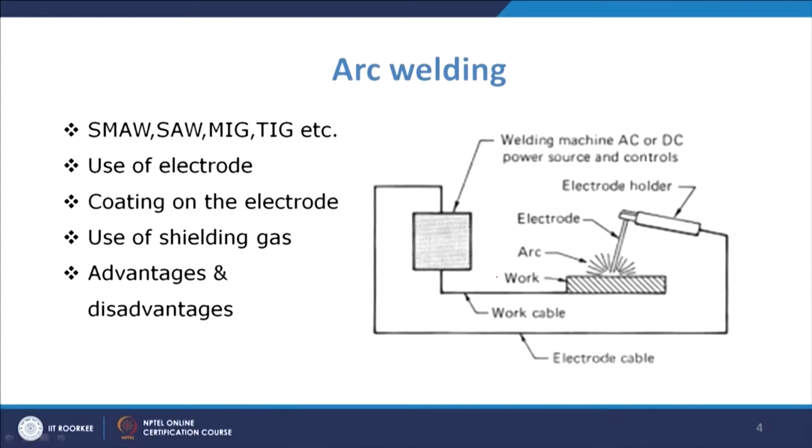So, another method, which is the most popular method, is the production of an arc using electrical energy. In that case, the arc is created, that is nothing but an ionized plasma, between the electrode and the workpiece. This arc has a sufficiently high temperature close to about 6000 degrees centigrade, and it strikes the material and takes less time to completely fuse it.